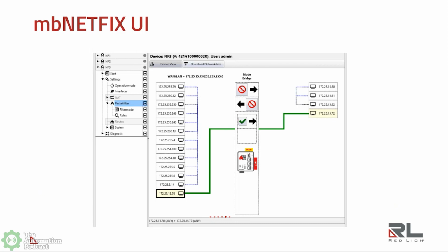And so when we're talking about using a radio like that, and then we're combining traffic that is generated on the OT or maybe even the IT side, some of it is broadcast, and some of that broadcast traffic can be quite chatty. If we have chatty broadcast traffic that's trying to go across this radio link, then we need to lock that down and prohibit it from going out the radio link, because it's just going to block up the low bandwidth link that we have that's not full duplex. So you can use a product just like this to allow or disallow, using that graphical interface, and say, hey, I do not want to allow this traffic from this host to go across this link, and then that will solve that problem completely.